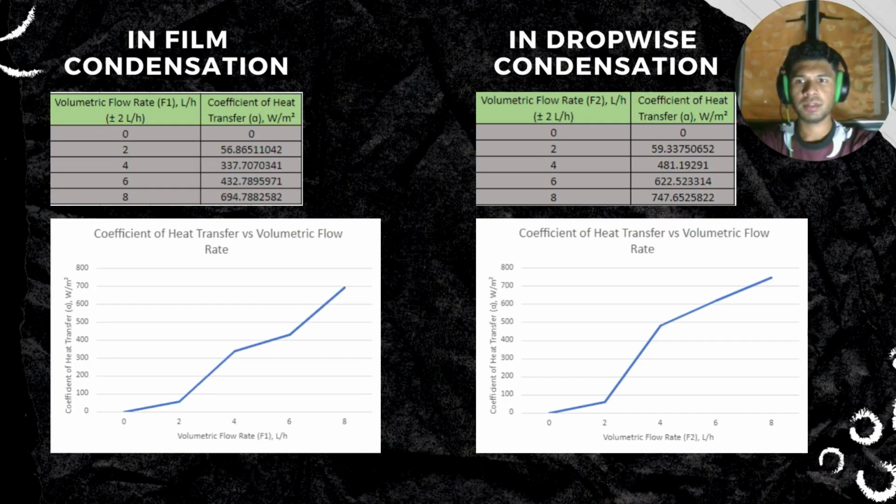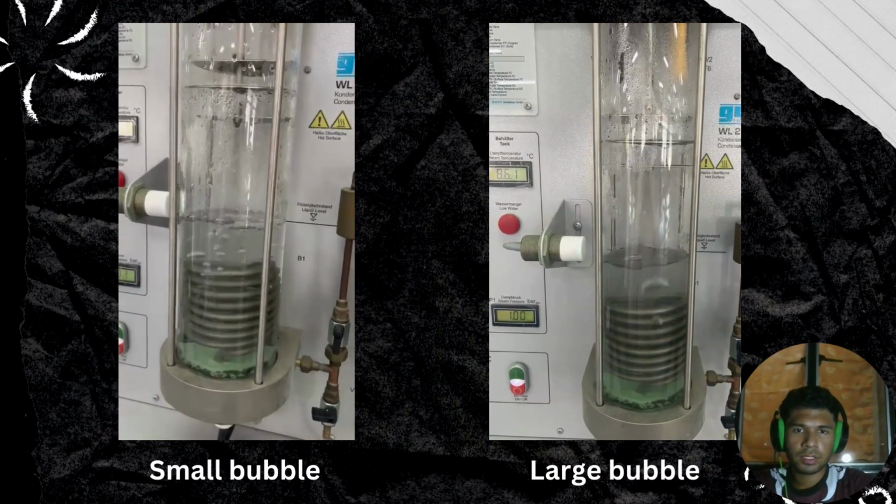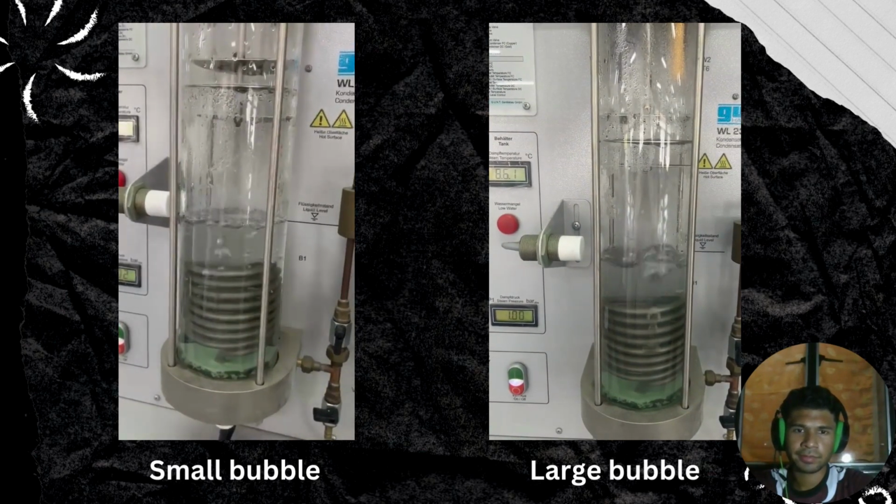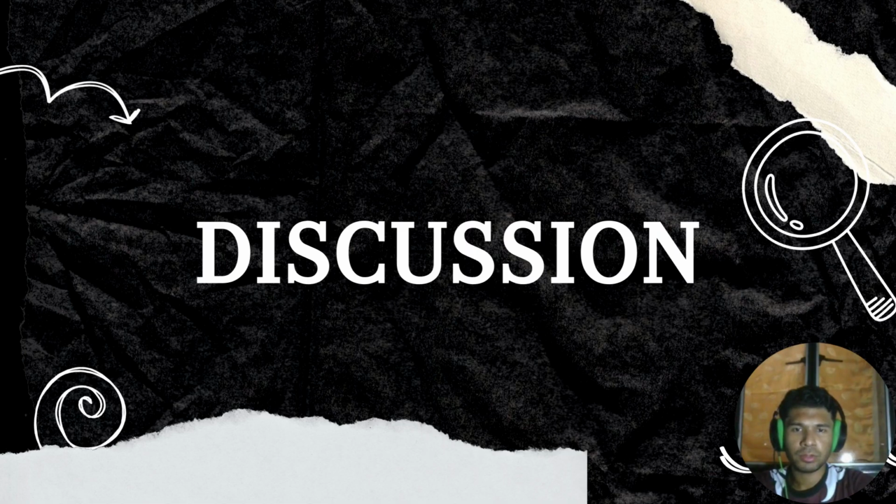In this experiment, we plot the graph of coefficient of heat transfer versus volumetric flow rate. On the left is the graph for the film condensation, and on the right is for the dropwise condensation. Both graphs are increasing. Between the two graphs, we can see that dropwise condensation is more effective than film condensation. This slide shows the comparison between small bubble and large bubble when we increase the volumetric flow rate. Without any delay, we continue with the discussion.